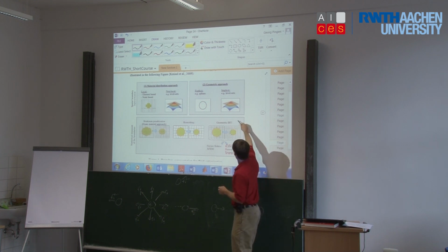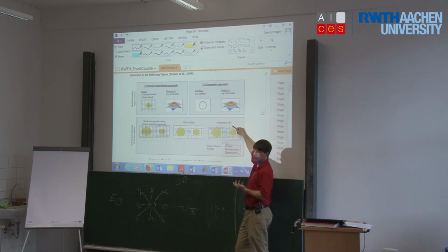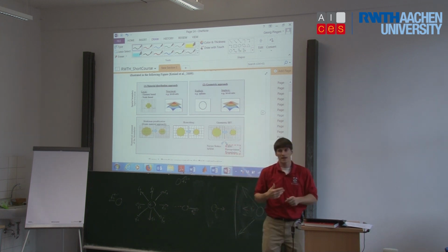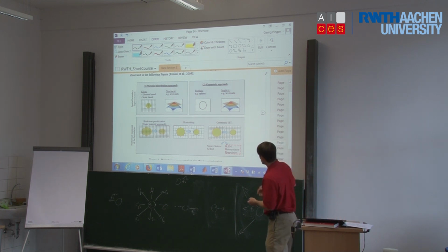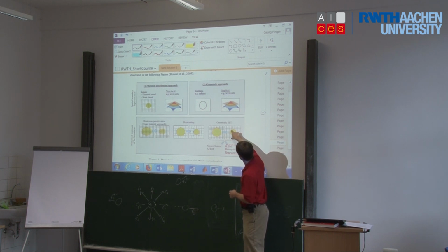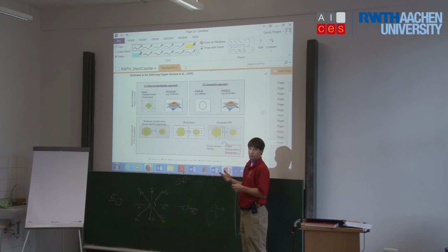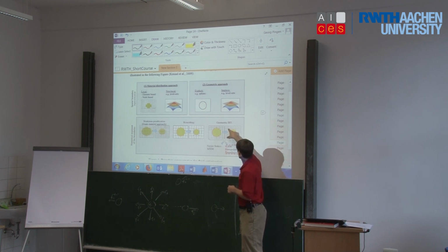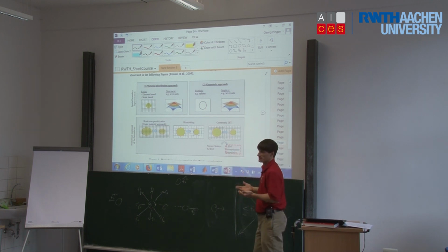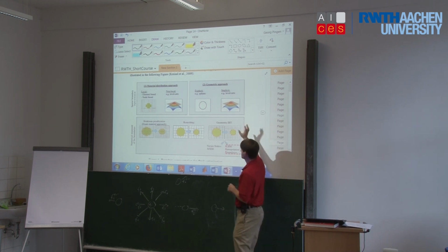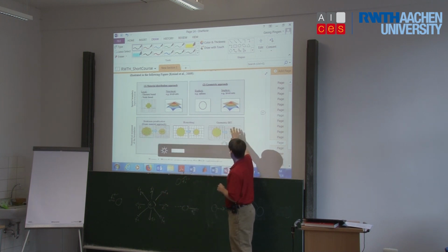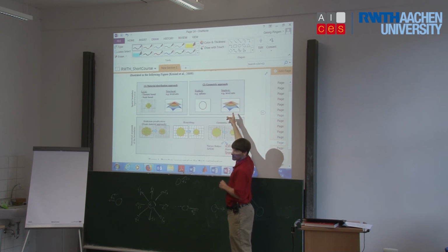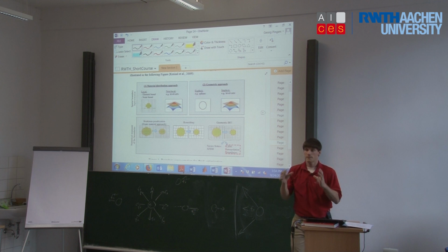Or we can use an immersed boundary type meshing strategy, which, if you're familiar with finite elements, would be like CutFEM or extended finite elements, where you can locally refine, or add additional degrees of freedom close to the boundary, so that you can put the boundary where it actually is instead of along your predefined mesh size. So there are several different options. I want you to be aware of those. For now, for simplicity's sake, we're going to use a porosity-based approach. A lot of research is now going in the direction of using level set-based methods with these immersed boundary conditions.